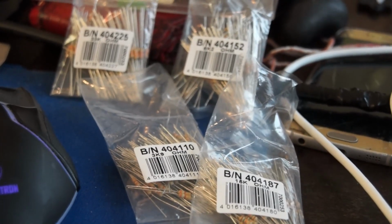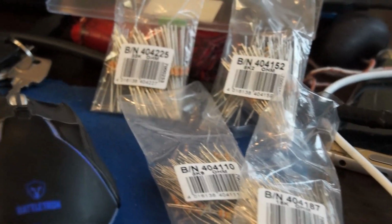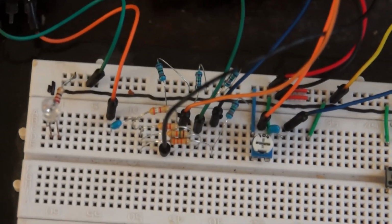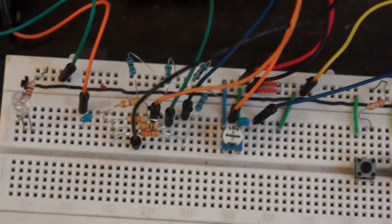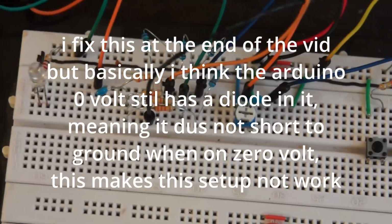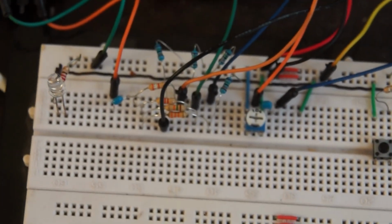And then I also have, these are the values that I used. I used a 4K, an 8K, a 15K, and a 32K. And then I used some 720K resistors, the blue ones, because I found that I needed to add a leakage current resistor at the pin exit that goes to ground. Otherwise they just didn't work properly. I don't know what the deal was with that.